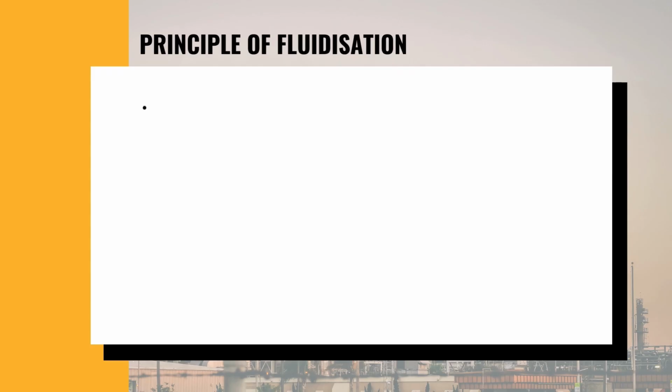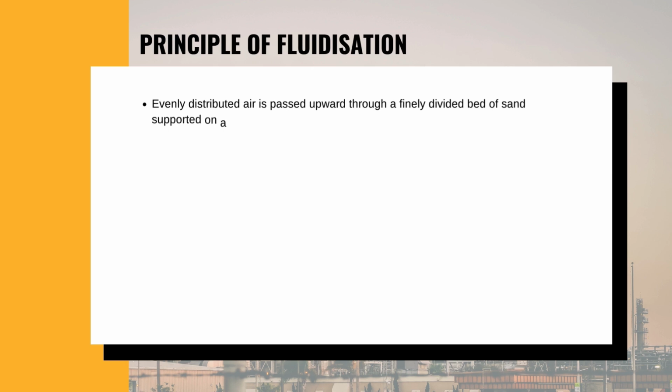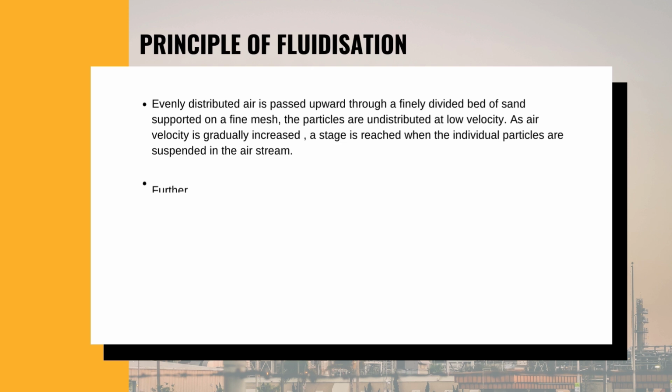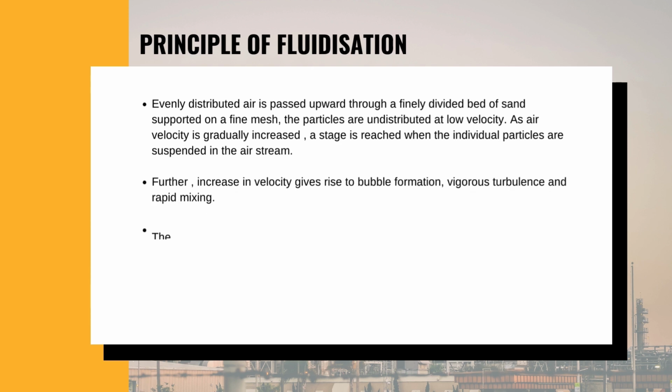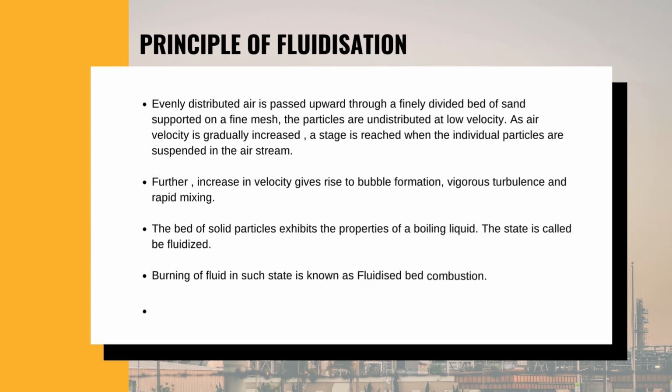Now, we will see the principle of fluidization. When evenly distributed air or gas is passed upward through a finely divided bed of solid particles such as sand supported on a fine mesh, the particles are undisturbed at low velocity. As air velocity is gradually increased, a stage is reached when the individual particles are suspended in the air stream. The bed is called fluidized.